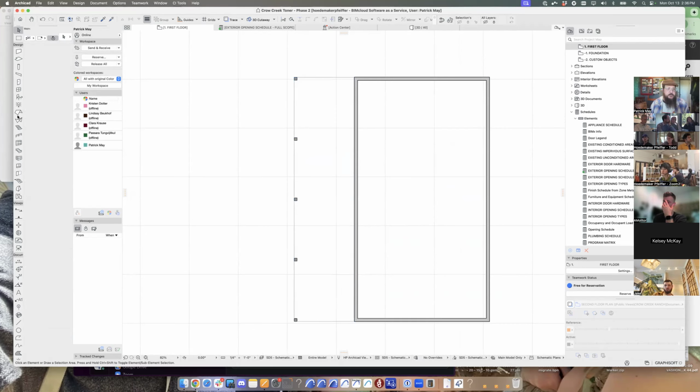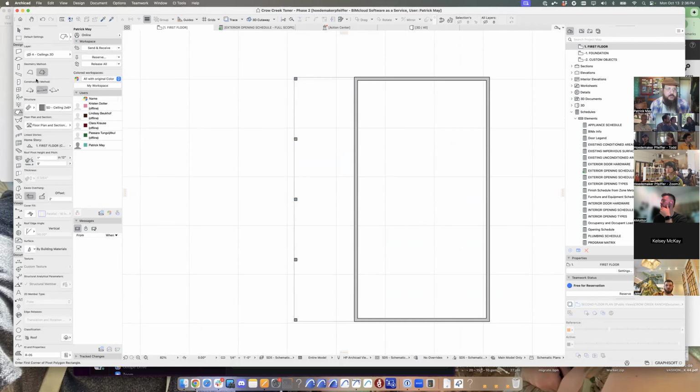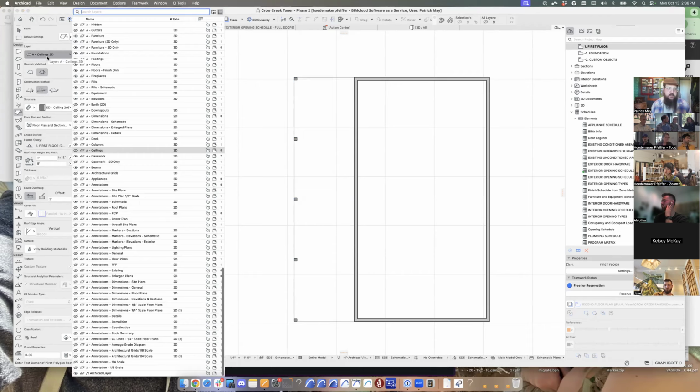All right, so the roof tool has a couple of different options here if we look at the geometry method. The first is the single plane option, which is the more complex, and then the other is the multi-plane geometry. The multi-plane geometry works pretty well most of the time. It's one of those options that works really well until it doesn't. It does have a couple of shortcomings. If your roof is any more complicated than basic hips and valleys, the multi-plane roof really doesn't work that great.